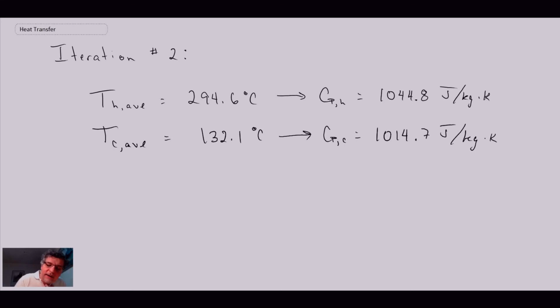When you do that again, you find that this is going to be the minimum fluid because the mass flow rates are the same. From this step on, you go through the exact same procedure again, and hopefully it converges after doing the calculation one more time. But that is an example of doing a rating problem using the Effectiveness-NTU method.